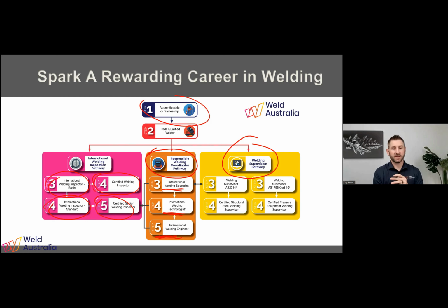It goes pretty in-depth in module 2, which is the materials. Basically material science, so it gives you a bit more analytical thinking. It starts looking into carbon equivalence and carbon phase diagrams and why things happen. Why has this material cracked? Why has this happened to you? What's going to happen if I use a different type of material? So it looks a little more at analytical thinking for the responsible welding coordinator. The Cert 10 on 2214 focuses more on the application of standards, preheating, post-weld heat treatment, things like that you might need on pressure vessels.